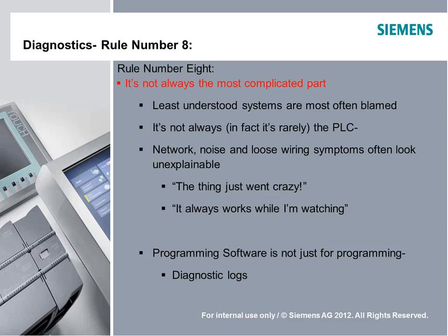If you run over the wiring with a forklift and dead short the output, that may not be true. So in other words, it's those hazard faults that actually create the problems, and typically they're not with the PLC itself, the CPU is what I'm talking about, but with its I/O, and that's much more likely to be causing the problem.